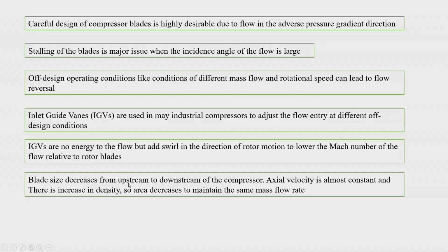In the direction of the flow, we know that we have to work with a compressor as a steady state machine. So, our mass flow rate at the inlet and mass flow rate at the outlet would be the same, but within that, in the axial flow compressor, axial velocity is almost kept constant in the direction of the flow. However, due to pressure rise, density increases, so axial velocity is constant, but density is increasing in the direction of flow.